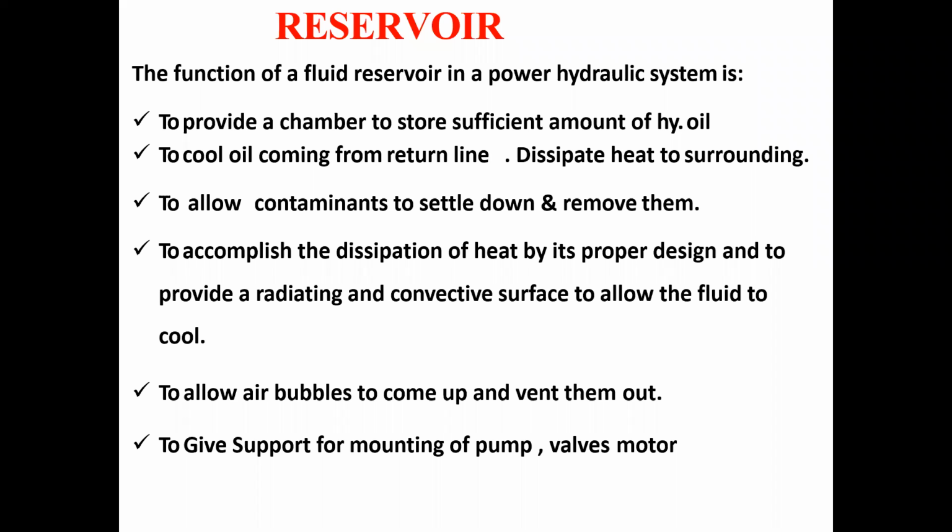Next is to cool oil coming from the return line, dissipating heat to the surroundings. What is its meaning? Normally the pump takes up the oil and increases its pressure. This high pressure oil is moved to the system. And as the pressure increases, its temperature also increases, because pressure is directly proportional to temperature. When this high temperature oil comes back to the reservoir and is sent directly again to the system without cooling, then the system will get heated, and if the system gets heated, then it will be damaged.